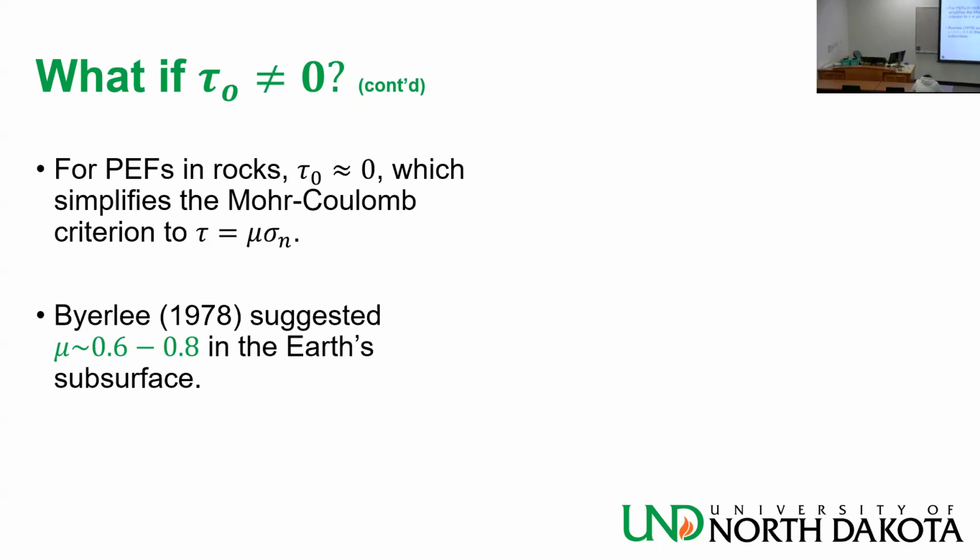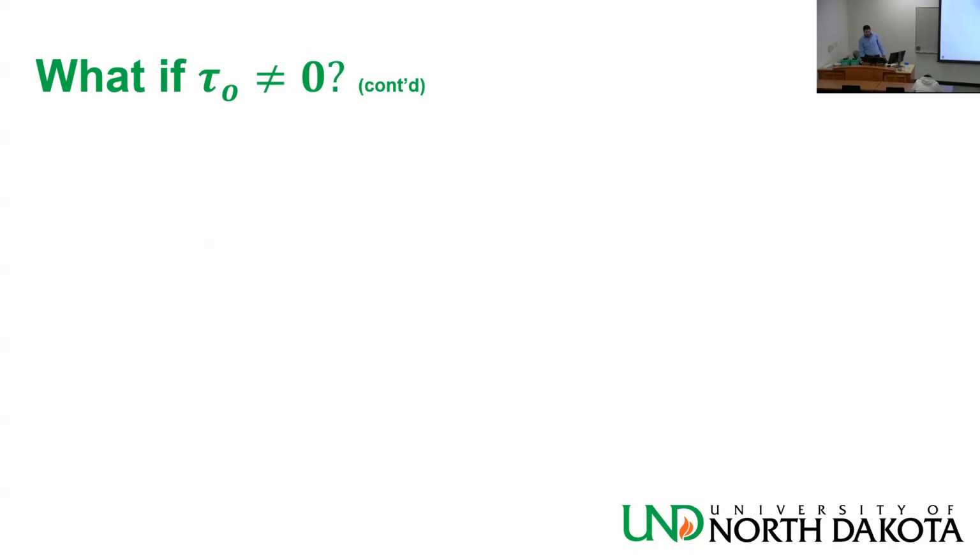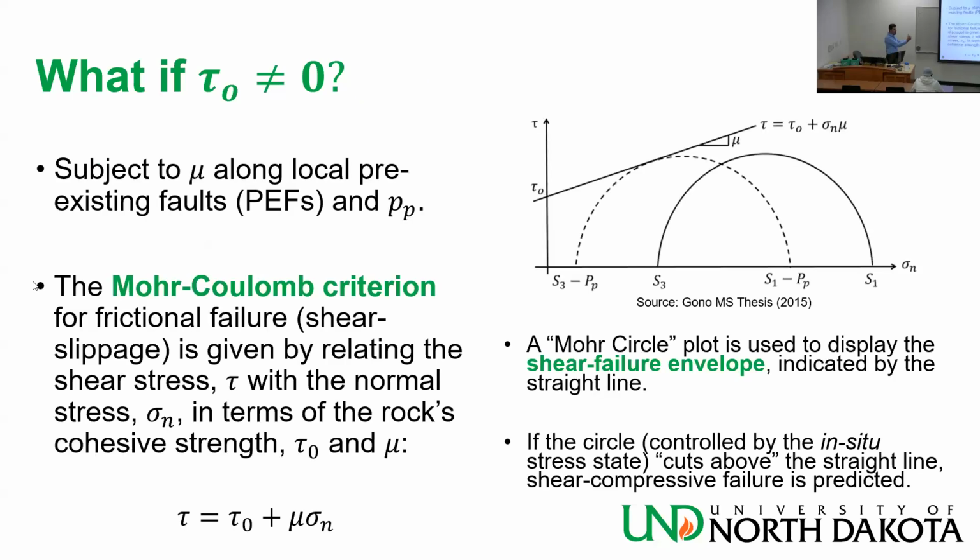Okay, let's go back to the previous slide very quickly. You see the impact of pore pressure? It moves your circle to the left. It moves it closer to failure, right? So imagine I'm moving like this. It moves me closer to failure.